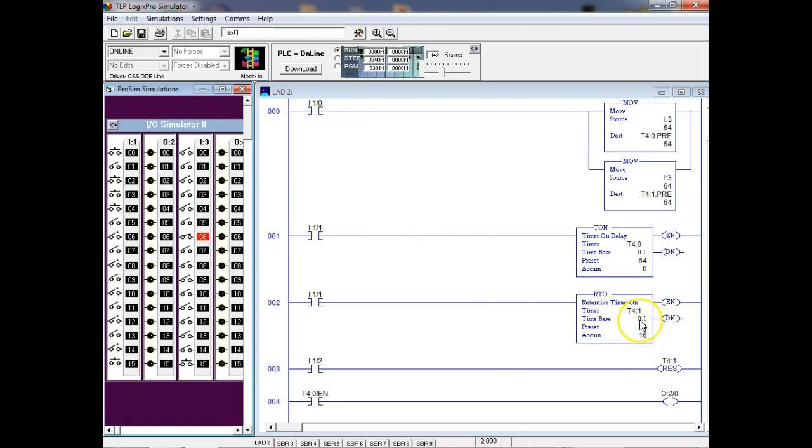It keeps this going. That's why it's called a retentive counter. So I come up here, enable it, disable it, enable it, disable it, enable it, disable it. So now I can go out there and do what? I might stop my line. I see something happen. I stop my line, but I still have to keep up with this time, right? You understand? And then I can go out there, make my corrections, hit it up, and the timer would start off from where it was at. That's the retentive timer.